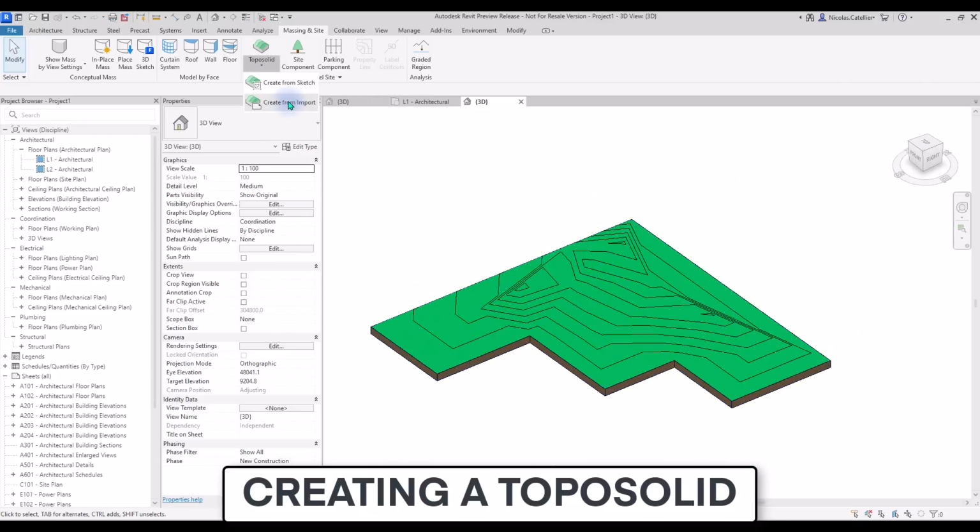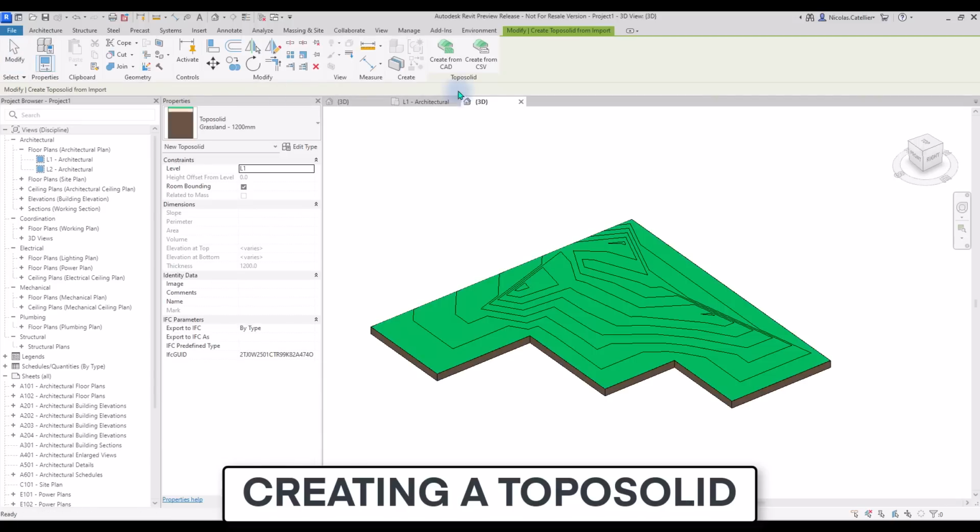As with the old Toposurface tool, you can also generate the Toposolid by importing a file. In the drop-down menu, select Create from Import. Pick either a CAD file or a CSV file.